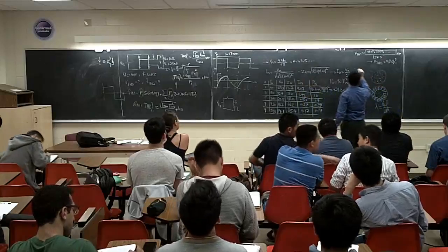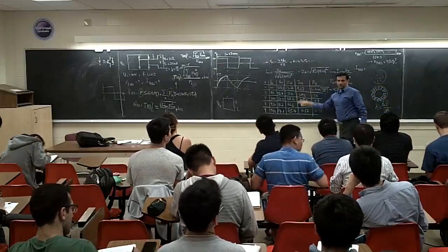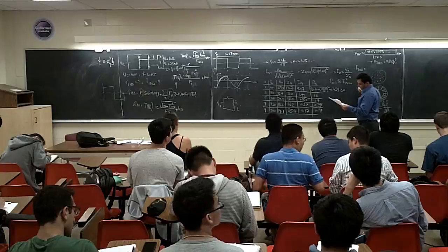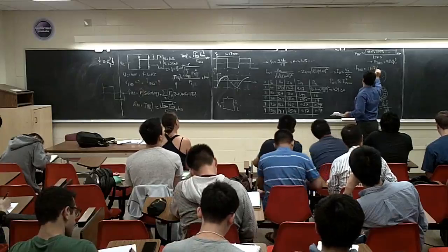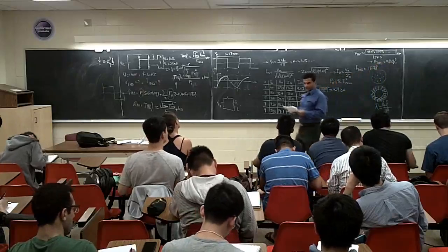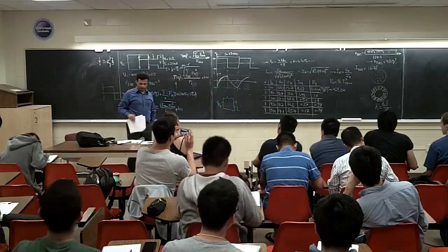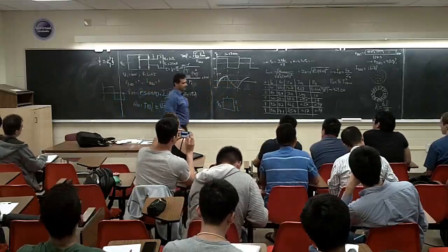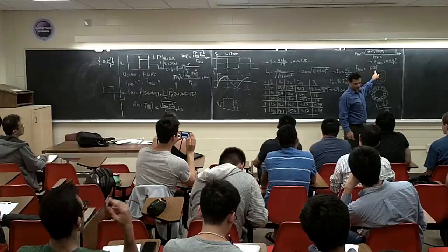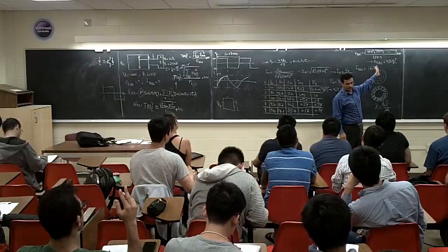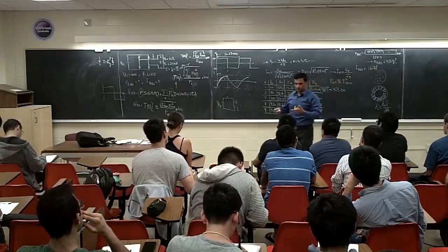But if you calculate the ITHD, basically you do the same thing. From here, if you calculate this one, ITHD is going to be 16.7%. So almost 1/3 of that, right? You can see the current THD is much better. The good thing is usually when they use the standard, they care more about the current. That's a good thing because the voltage is really difficult to bring down to 5%. But current is easier because when you select a bigger inductor, it's going to help you.